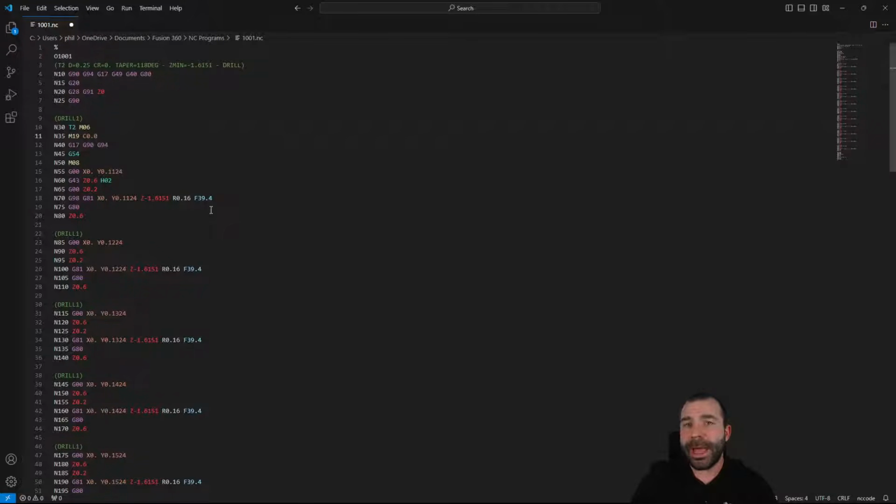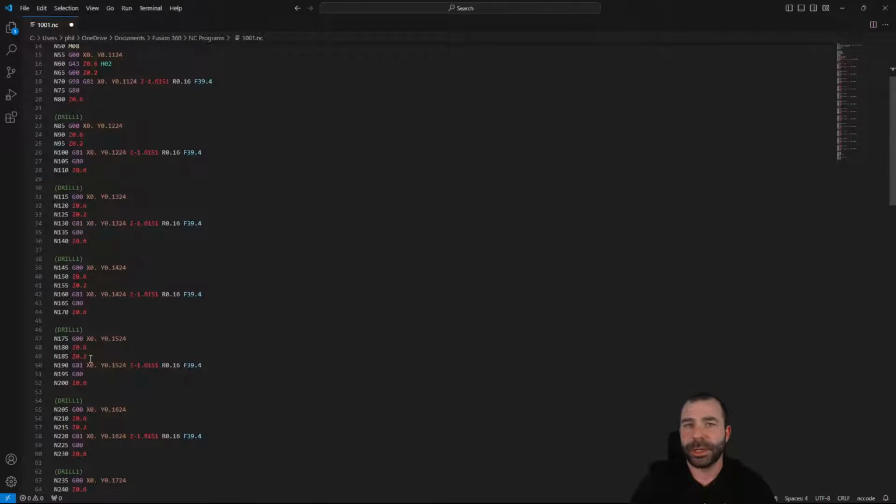Now, if we wanted to pattern even further, and I'm not going to show you guys this because you can reach out to me directly, if we did a circular pattern, we could actually output the C axis automatically to broach, say, a star pattern, or if you needed to do a spline type of situation. So again, by removing the spindle speed, we're not turning our spindle on, we're locking our spindle, clocking our spindle, and then we're just running through our cycle.